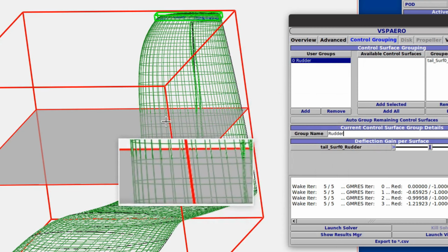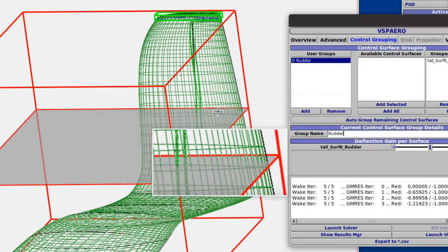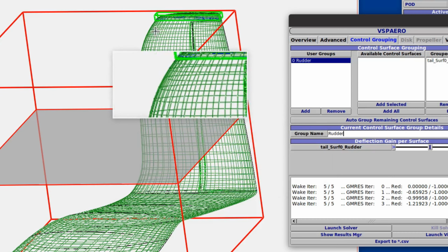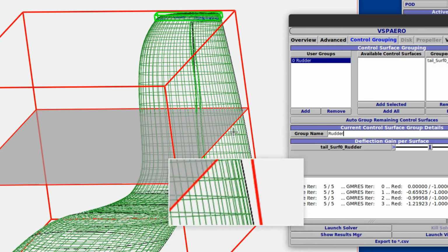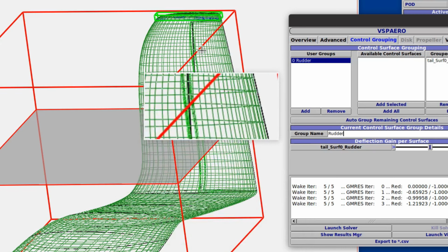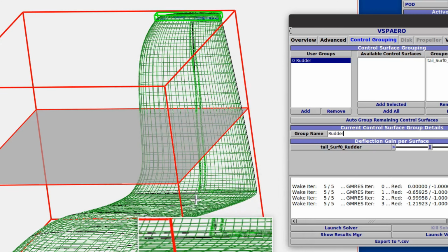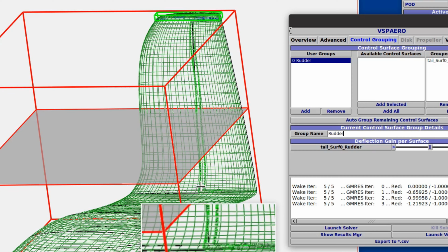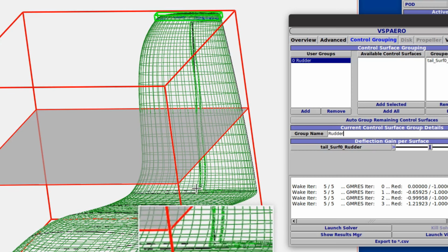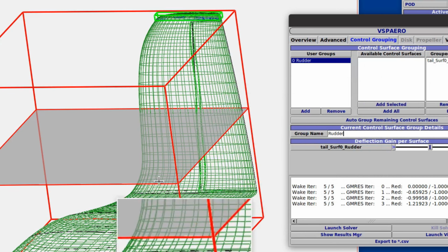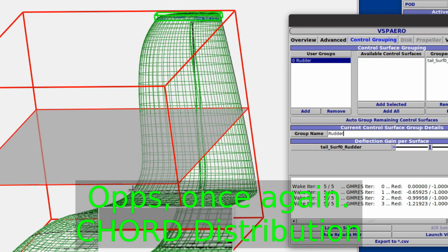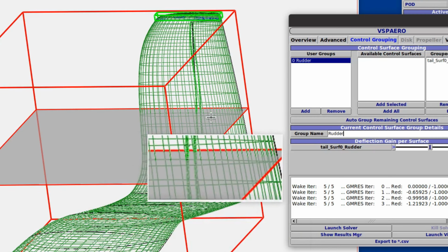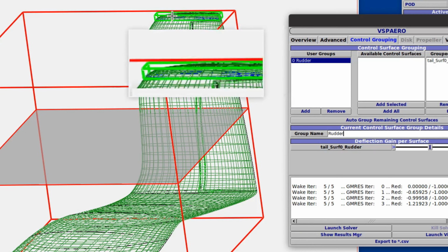I got to get this chord load information in at least one place, and I should probably get it in several places. Now, according to the FAA, you really only need to do one estimation, and then it works all the way across here. Now, I happen to know from looking at some pressure values that I did using the panel method that my span distribution is not the same down in this area as it is in this mid area.